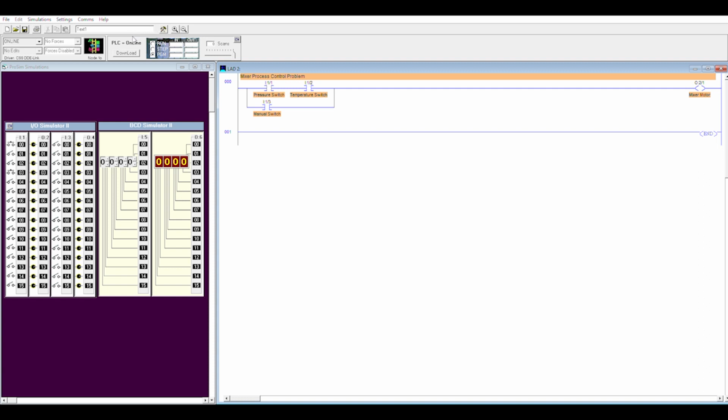From the PLC's perspective, though, we don't have this program. It only exists in our computer. So let's press download, to download that program from the computer to the PLC. Nothing really indicates this has been successful except for the fact there were no errors. With most simulators and PLCs, we're going to see a change here when we move to the run mode. We're going to see these bars change color. Not with this simulator. It's just going to change to the run mode.